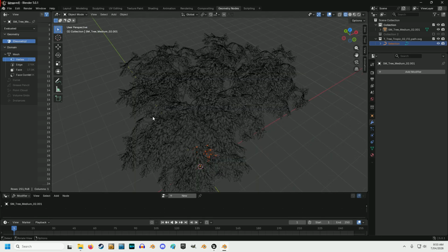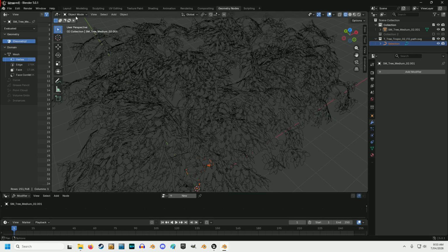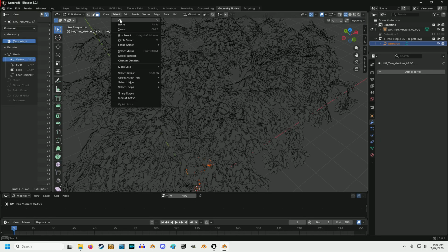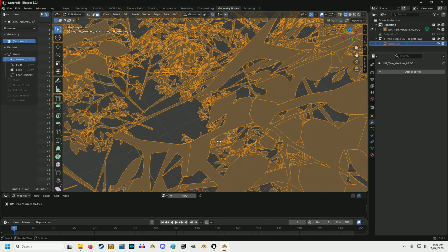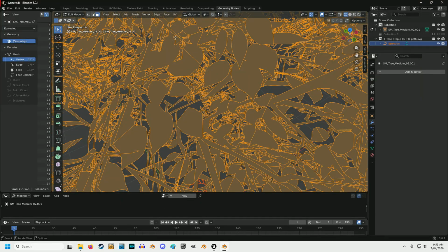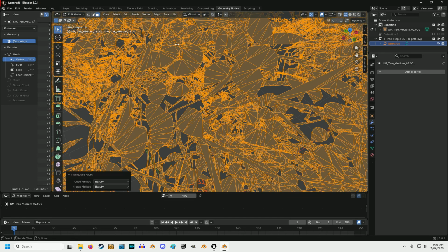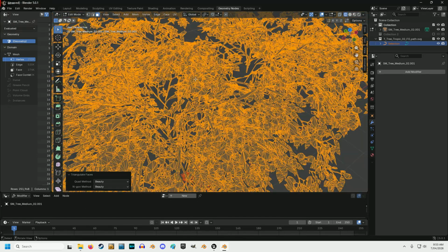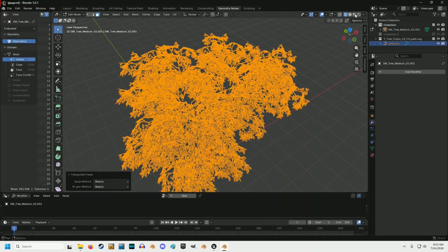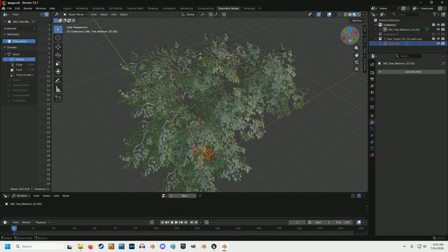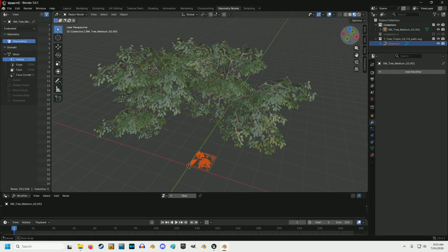Okay, that's done. Now we need to go back into our edit mode and select all, and now we're going to retriangulate this so that we get a nice triangulated set of faces. And we go. That is it, and done. So delete, select none of them, go back to object mode, and we're done with our cutting and everything else.